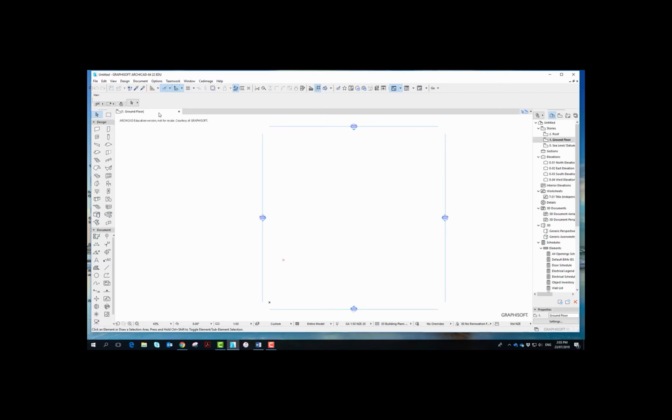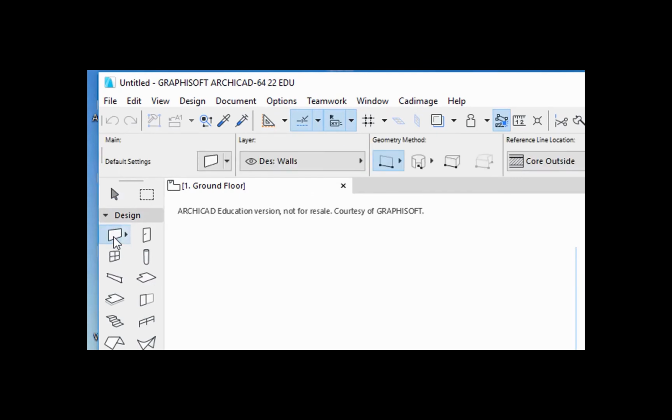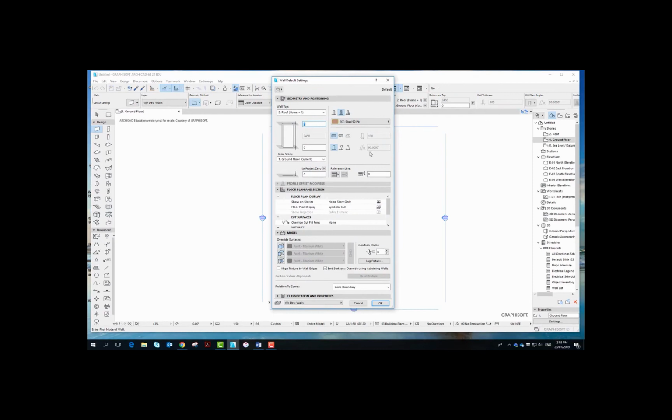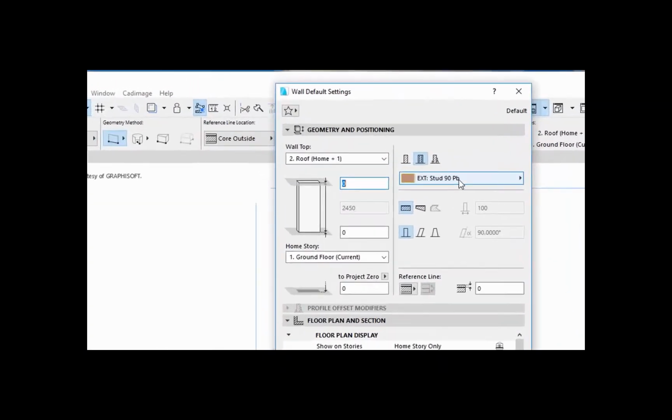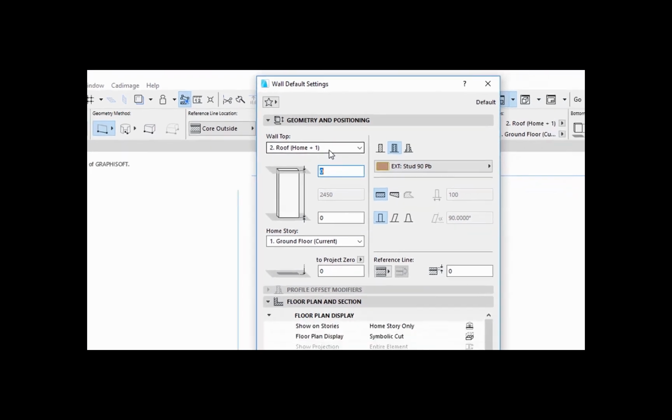So if you look at what Archicad tells you in the manual, you can double click on the wall tool or click it and click this one. You get the same result. It's these settings. Now, don't worry too much about some of the things in terms of having plasterboard. We'll just use the instructions the manual gives us, but in class you might be shown how to tidy things up a little bit more. So if we use the settings, the roof is fine.